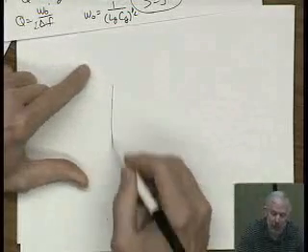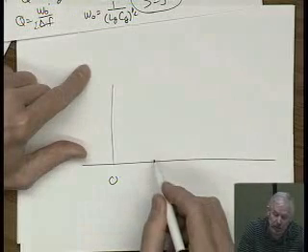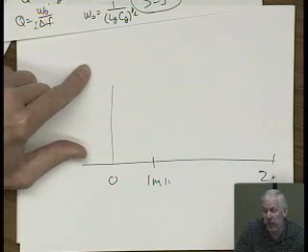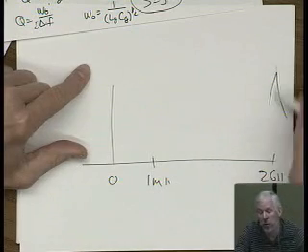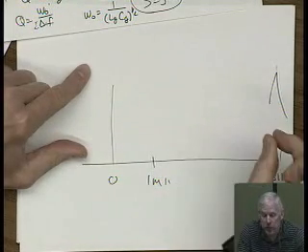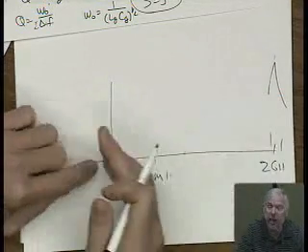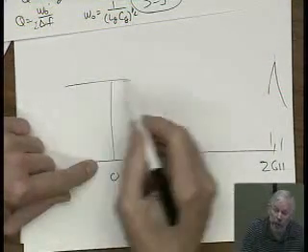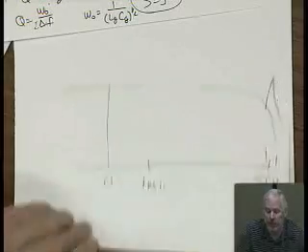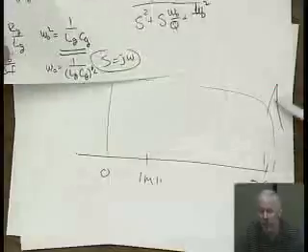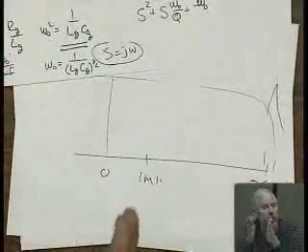You start plotting stuff. This is 0. Here's 1 megahertz. We're way up here at 2 gigahertz for these cell phones, and that's what we're interested in, only around that frequency way up there. So we can design circuits that are tuned to 2 gigahertz. If we had to have a circuit that worked all the way from 0 to 2 gigahertz, you can't use these tuned circuit approaches. These only work around some narrow frequency value.